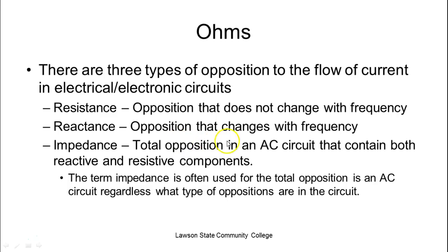Reactance is the opposition that actually changes with frequency. So reactance is dynamic. Resistance is static. I can put a different frequency on a resistor, and a 100 ohm resistor will always give me 100 ohms. A device that is reactive gives me a different resistance depending on frequency.